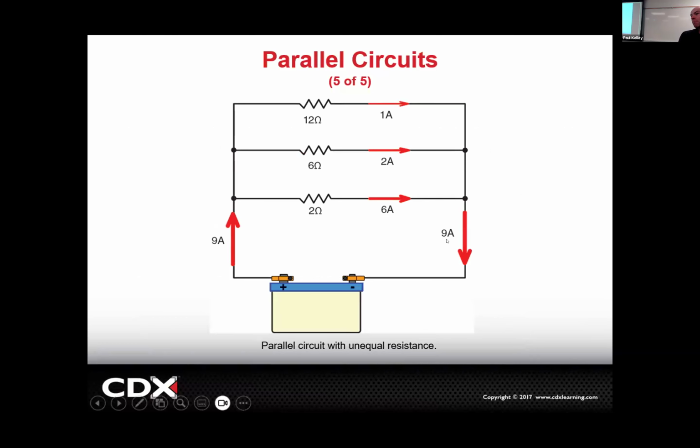And on the ground side, the same. That's the other thing. If you aren't using a chassis ground, you've got to remember your ground wire size has to be good for the return path as well. We get a little spoiled in automotive because generally what we'll do is we'll just land this thing in the chassis ground, and the chassis is so big, so massive, it can handle all the electrons you could throw at it. We're not normally real worried about the ground, but if it's an event where you have to actually run wire to support the ground, you better make sure the wire size you use is good for the 9 amps or whatever the calculation is.